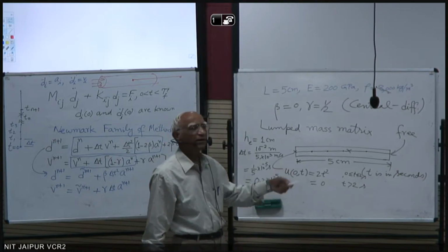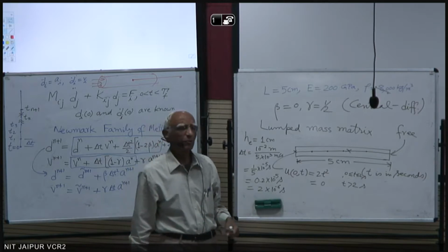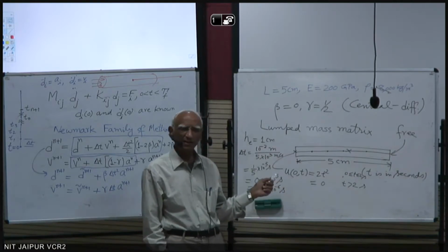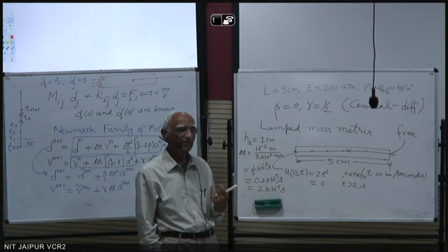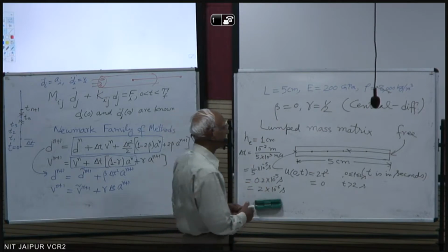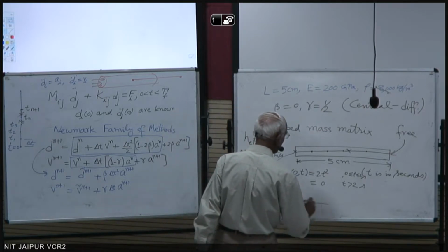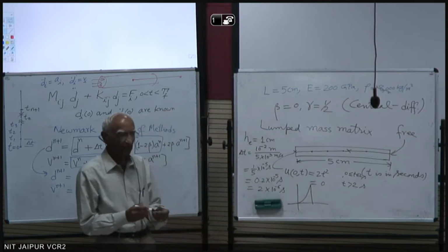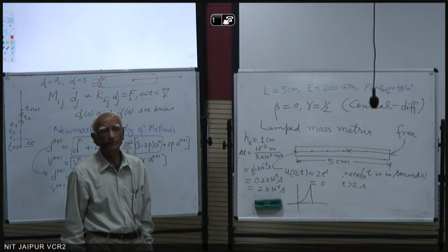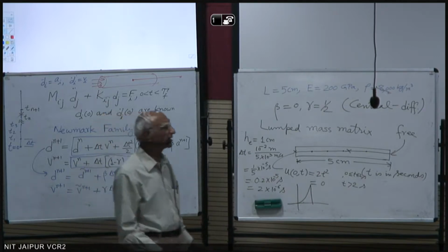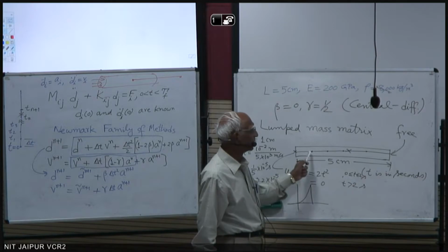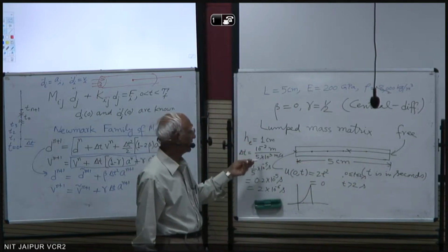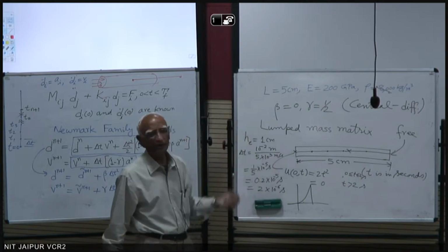There were a few questions raised, how will we apply acceleration? So that's why we are imposing displacement boundary conditions rather than the pressure boundary condition. The displacement is something like this, you are imposing like that, and then you suddenly drop to zero. Let's see what we get. The main thing is to see initially if you get something moving to the right at the speed of 5,000 meters per second.